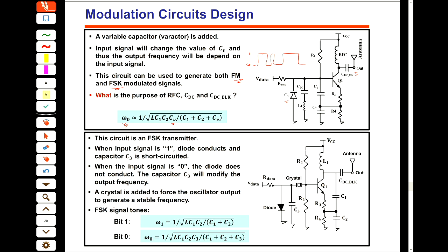But if it's not saturated and then it changes, then the frequency which is going out is changing. I mean, you are expecting to send your data at F1 and F2, but then it goes to F prime 1 and, for example, F prime 2. But if we make sure that these two levels, level 1 and level 0, are not changing and exactly stuck at one point, then it's fine.